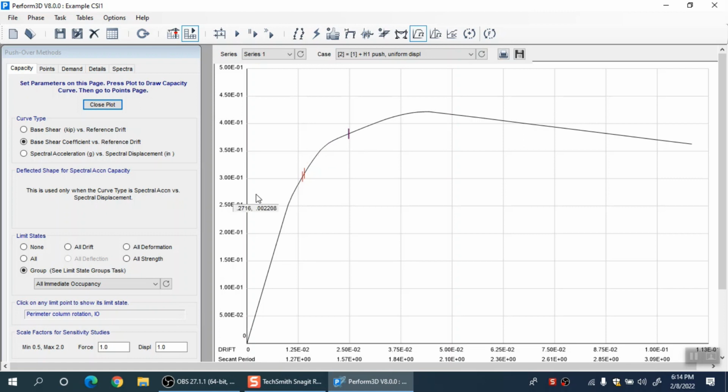So this complete curve gives you the overall life of your building. What is going to happen to your building if the load exceeds a certain level, such that the building is going to get completely collapsed. At this last point you can call it a complete collapse of the building, because the building is no more taking any further load and it is going to go down to an exceedingly high deformation level, right.